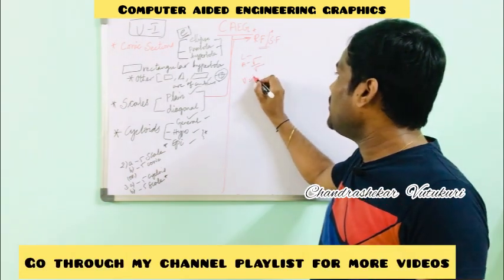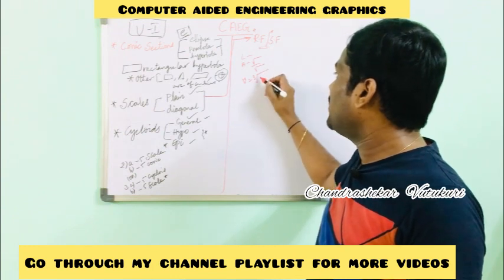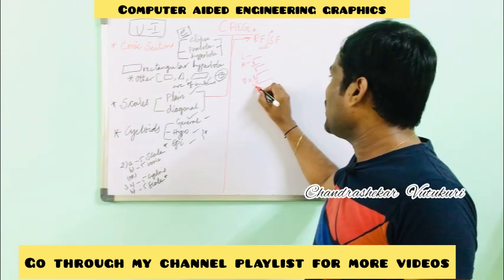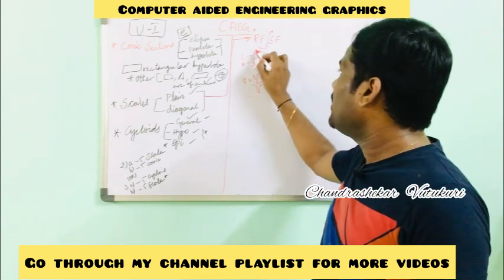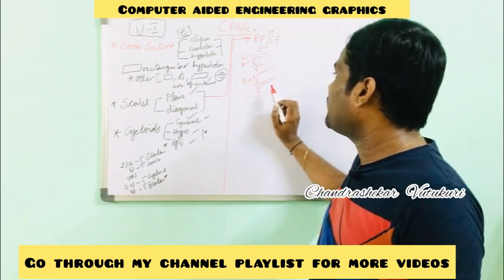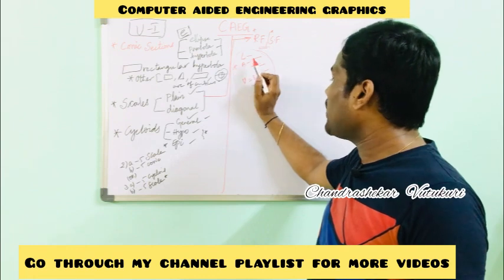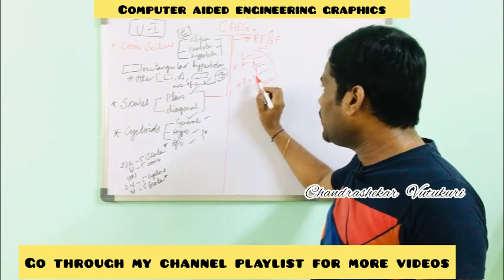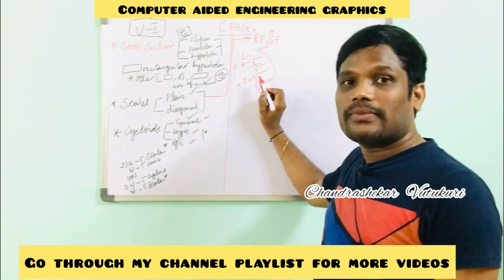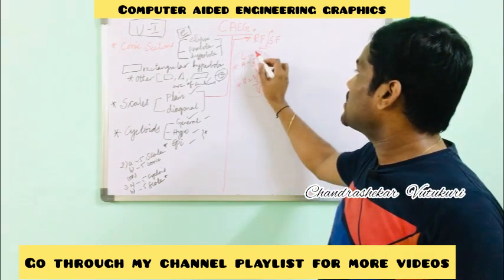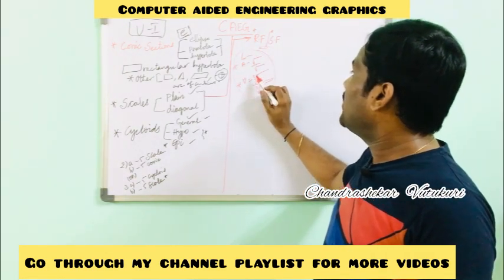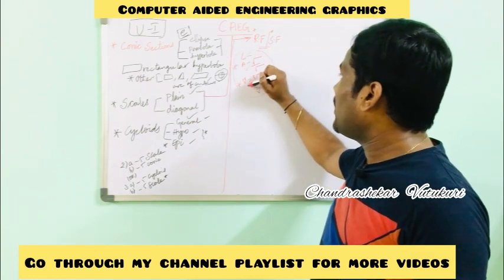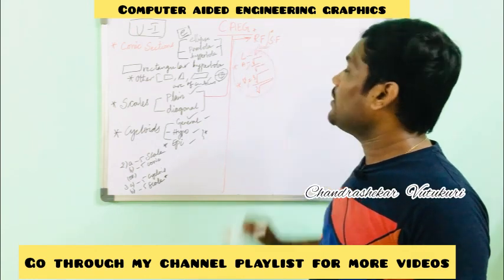And if it is volume, it is the cube root of the volume of the drawing by the actual volume. These 3 things are to be remembered. Sometimes they will ask in terms of length, sometimes a map, or sometimes in terms of fluid or something. So this is the way you are supposed to work out the length, area and volume related to RF.